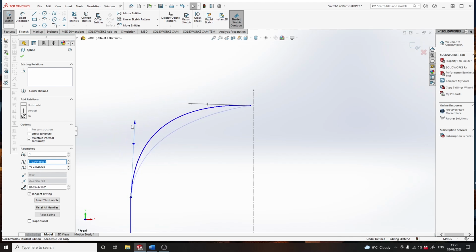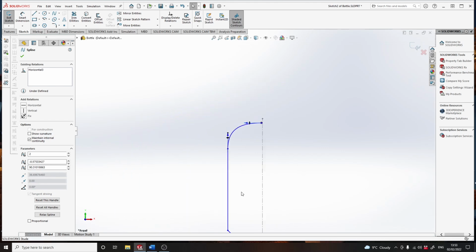And you can use this to make the shape of your bottle. The key thing about the bottle geometry is that actually this is a tangent here, this curve. So this thing has to be straight up, so it's no good doing it like that. That's not realistic. So what we can do is set a constraint on it. If we make that handle vertical, and if we make that handle horizontal, we can now just control the weight of them, but we get a kind of a sensible design for our shape. Okay, that's the ones at the top.